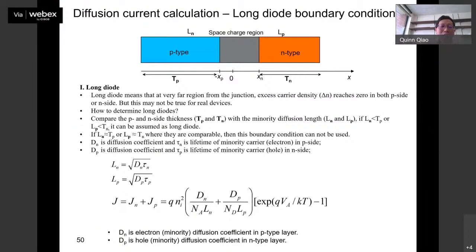That's why under different bias, the tunneling becomes more significant, and that's why you see the current flow. There should be blocking, but now there's some current flow in reverse bias. That's what you see there. It's either because the interface has a defect or there are tunneling spots between the zinc oxide and the P-type silicon. You look at the band structure, you can study that.